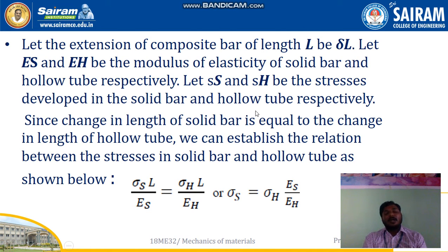Whenever the change in length takes place in the solid bar, it will be equal to that of the hollow tube. Based on this condition, we can establish the relation between the stresses in the solid bar and the hollow tube as shown below. Since the change in length of the solid bar is equal to the change in length of the hollow tube, we can establish the relation between the stresses.